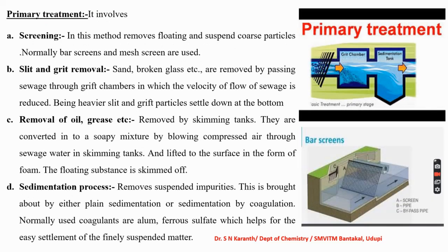Here, you can observe that the primary treatment involves four steps: screening, silt and grit removal, then removal of oil and grease particles, and then sedimentation by coagulation. First is screening, the second is silt and grit removal, then removal of oil and grease, then sedimentation.